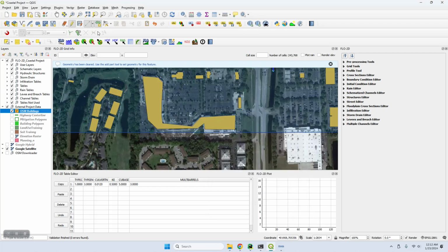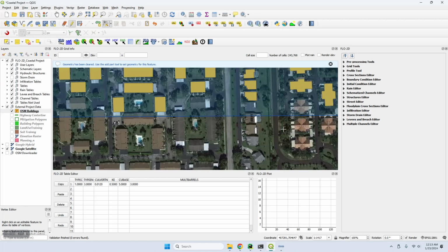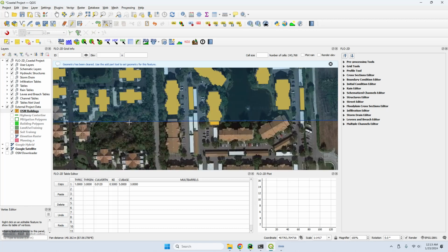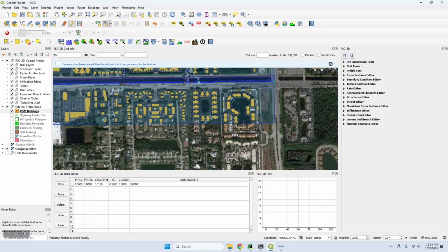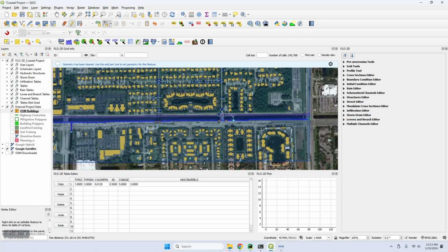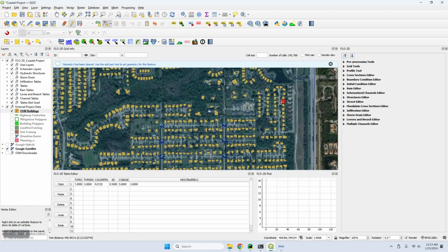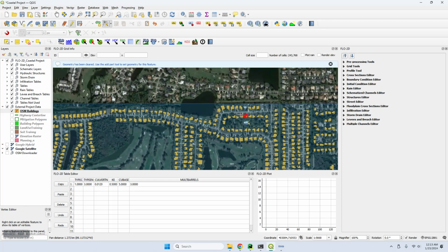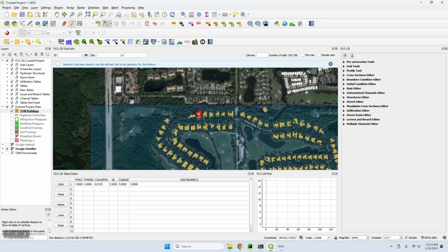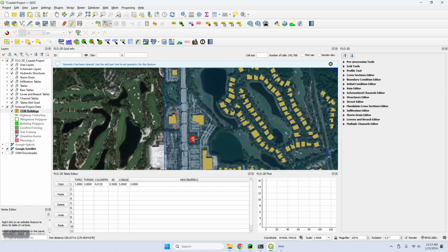And then if you don't like that, you can just do something like that. Kind of just get it a little better. And again, what we're looking for is ones that cross the boundary and getting them off the boundary. So back to our vertex selection tool and just getting rid of those ones that are crossing the boundary. We'll check our top boundary. I thought we did a really good job up here. Yeah, and then we'll check our side boundary.